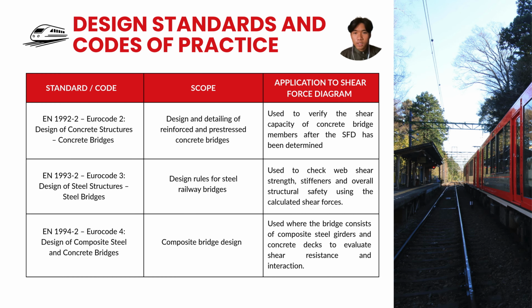So the next slide is the design standard and code of practice. We include three codes of practice here. The first one is Eurocode 2, design of concrete structures and concrete bridges. The scope here is the design and detailing of reinforced and pre-stressed concrete bridges. What is the application to the shear force diagram? It is used to verify the shear capacity of concrete bridge members after the SFD has been determined.